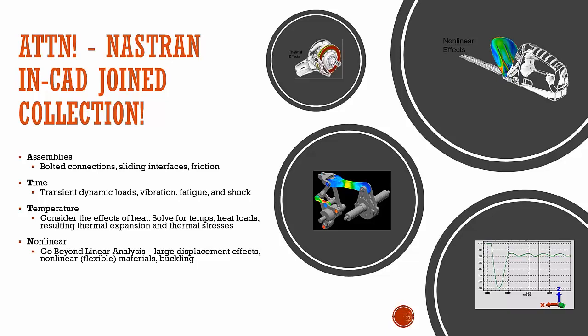We can put in constraints that include the bolted connection geometry already. Basically, we can simplify the complex geometry, take the bolts out of the model and use the Nastran simulation bolts for the assembly. So we can reduce modeling time, and the simulation is quicker if we use that method rather than physically designing those bolted connections in the assembly.